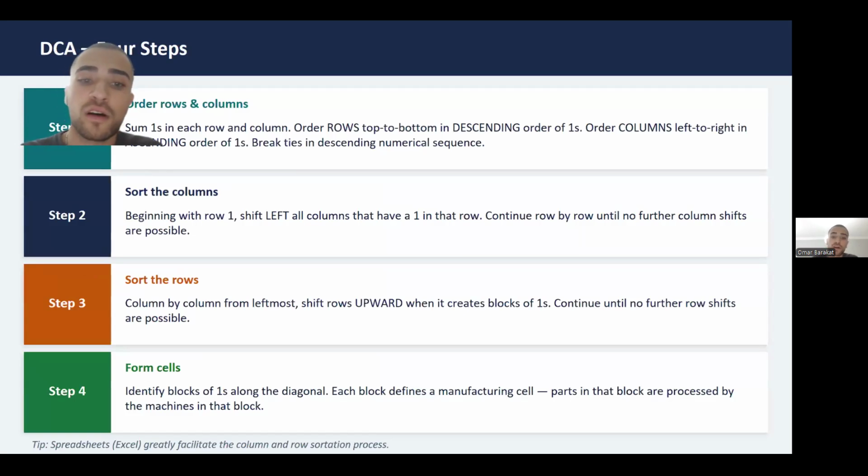The full benefits of cellular manufacturing are achieved when cells are designed, controlled, and operated using 3 principles: just in time, total quality management, and total employee involvement. Together, they can produce 3 categories of outcomes: reduction, simplification, and improvement. Every one of these reductions and improvements feeds directly into facility design decisions. Fewer machines needed, smaller building footprints, less storage equipment. The cell is not just an operational concept, it's a facility planning tool.